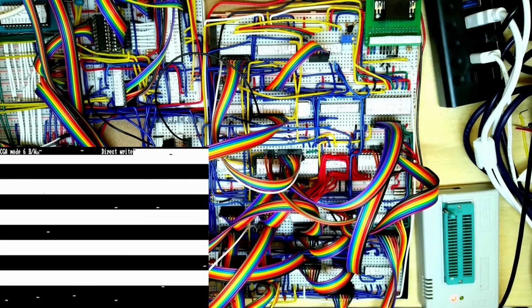So these initial tests show that we've got pretty good compatibility so far, but there's a few issues we need to fix, and also need to change the clock so that we can support the 40 by 25 column mode in the full width of the screen, so we need to adjust the clocks for that. Once we've done all these changes and fixes, then going to run a utility called CGA Comp, and this basically tests compatibility of the card with a number of issues, and so hopefully at the end of that we'll actually have a much better idea of how well our card is performing.